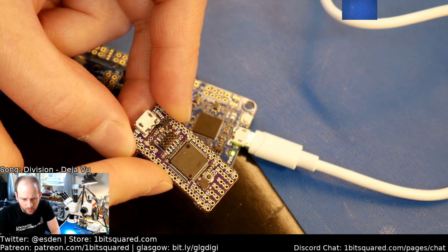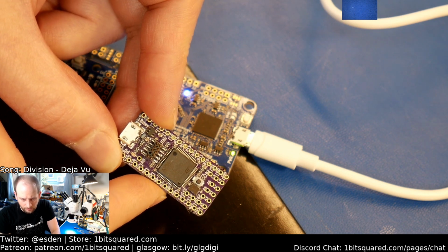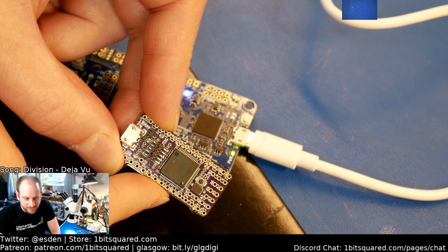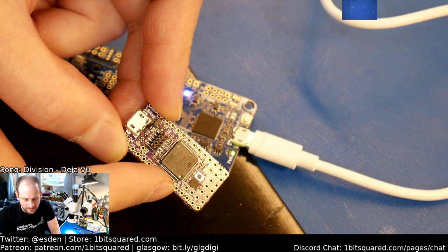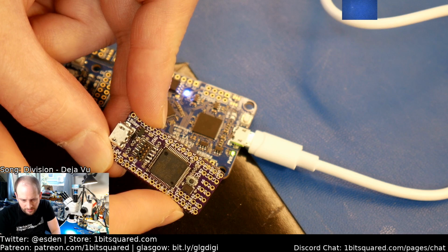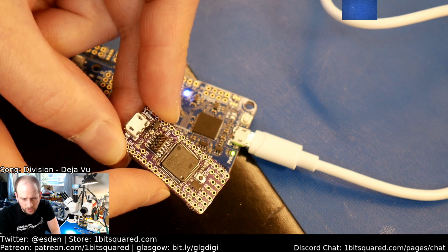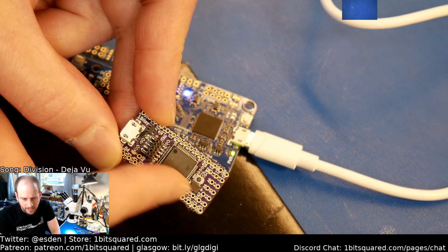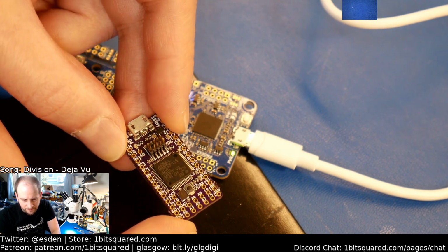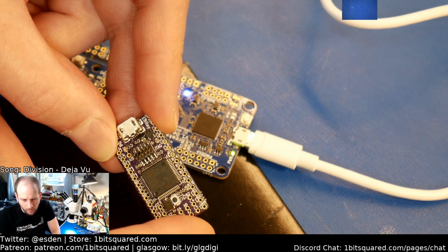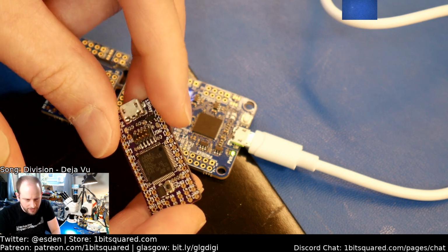At that time, most boards that you could buy, or most development boards, either integrated their own debugger on board or didn't expose the JTAG interface. So you could not just take a Blackmagic probe, connect to it, and play around with JTAG with the native Blackmagic probe. So I made this board based on a UAV autopilot that I was making at that time. And so it has a similar footprint as the Teensy, with an additional row of holes because I had more GPIO. And that's the 1-bitsy.